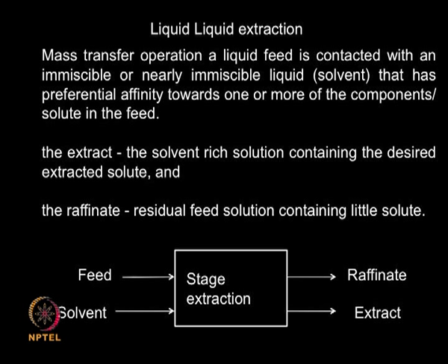It does not require high temperature or pressure, it is done in ambient conditions. So it is very ideal for solutes which are very temperature sensitive. It is very ideal for proteins because proteins will never get denatured. So it is very widely used technique, except that the solvent should not denature your protein of interest. Sometimes the solvent may take away the water present in the enzymes, thereby denaturing your enzyme or protein. So that is the only point you need to keep in mind.